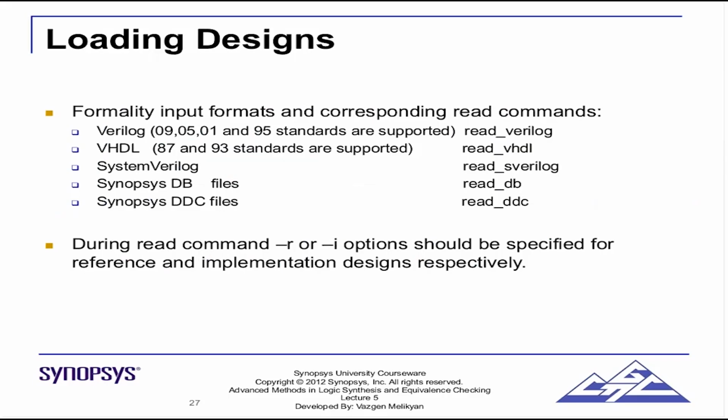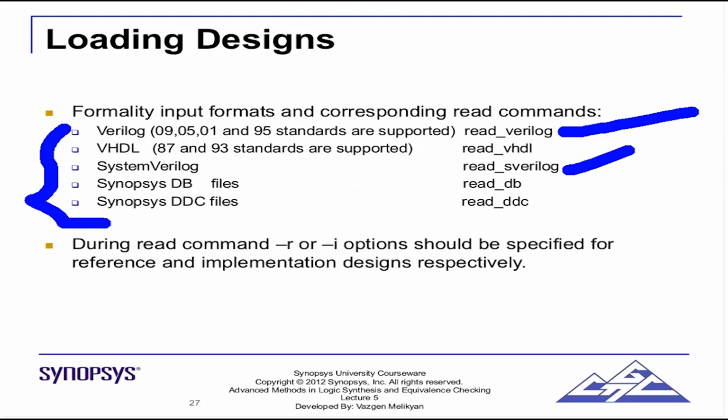Now when you load the designs, it supports many formats. For all practical purposes, you would probably be using Verilog, so you would be using read_verilog. During the read command, you have to give -r or -i to tell Formality whether this is a reference design or the implementation design, right?